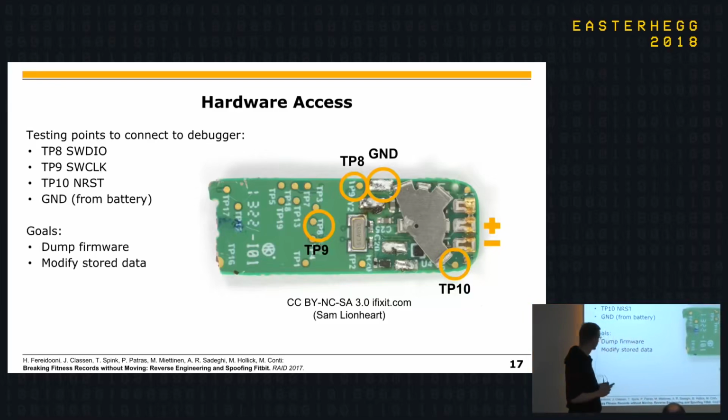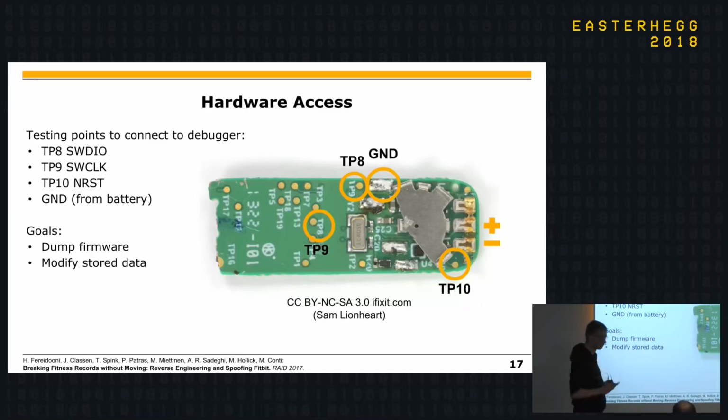So with this, we are able to dump the complete firmware, and we are also able to see what data is actually stored inside your firmware or inside your Fitbit Flex. Also important to note, we will talk here about the Fitbit 1. So this hardware is about the Fitbit 1.